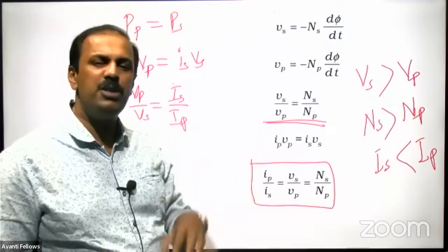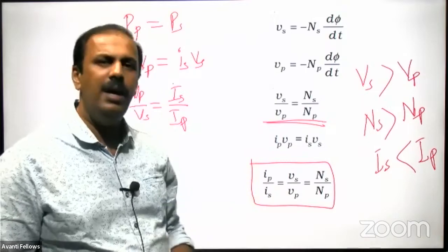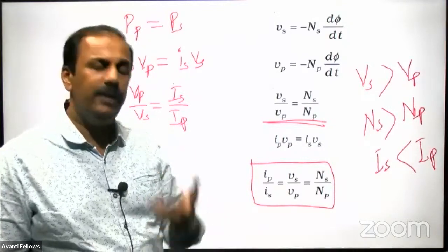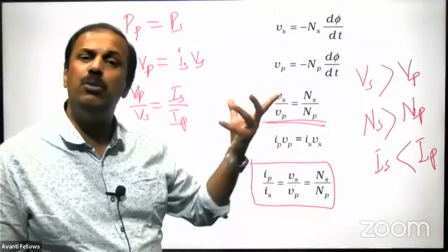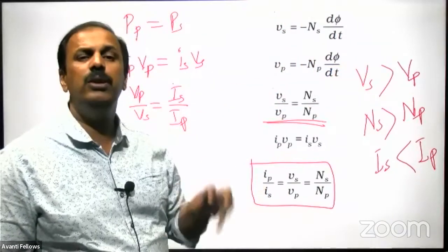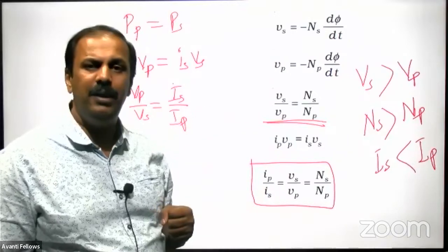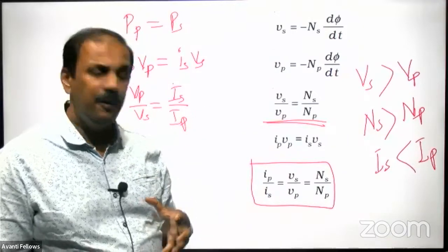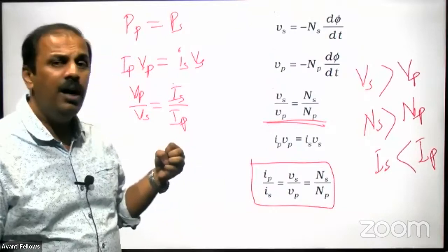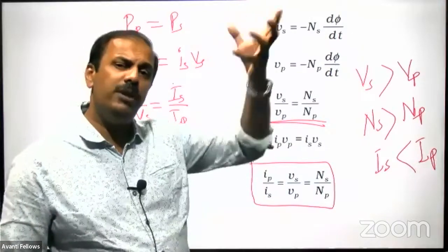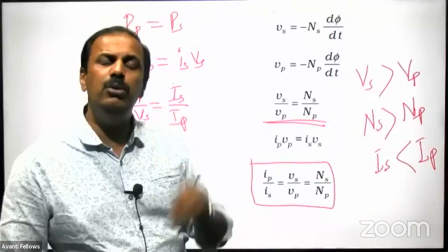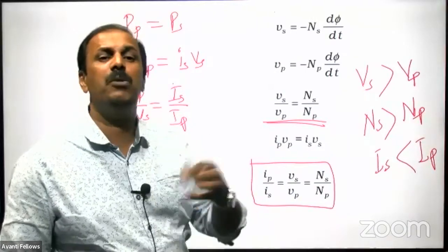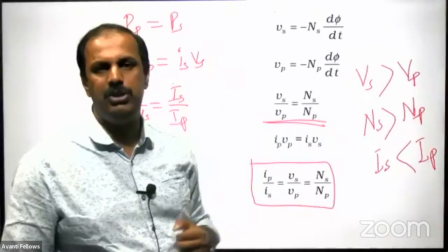So we have a power station where we are producing the power. After producing the power, we have to transmit that power somewhere. Just now we discussed that the transmission voltage should be very high. So in order to increase the voltage to a high level, we need a step-up transformer. The use of the step-up transformer is in the power station to increase the voltage.